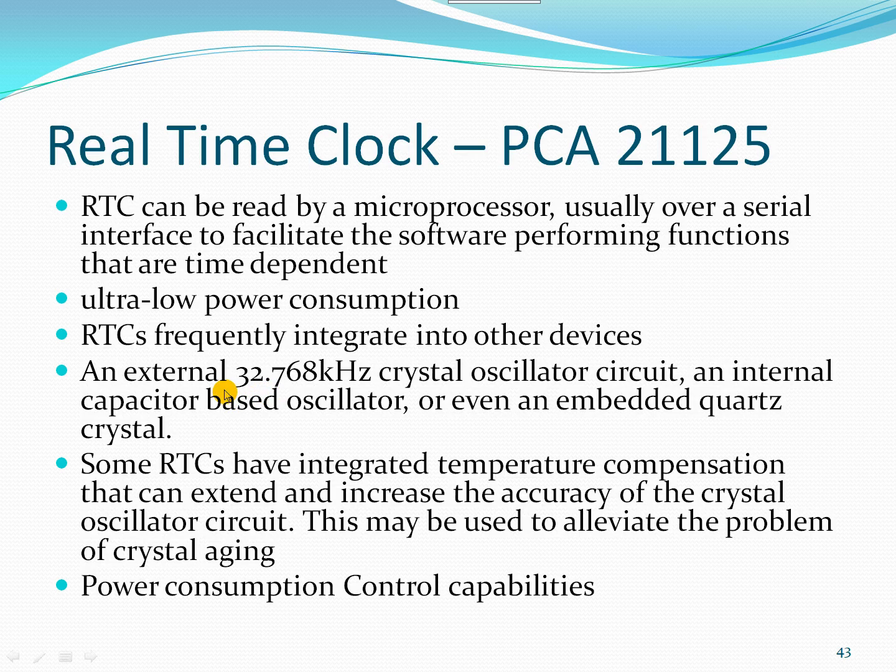And they can be frequently integrated into other devices, and an external crystal oscillator of 32.768 kHz can be used, but using this quartz crystal may be somewhat temperature dependent, because depending upon the load of the microprocessor connected through the serial communication, the crystal will be loaded at some time, so that the temperature may rise.